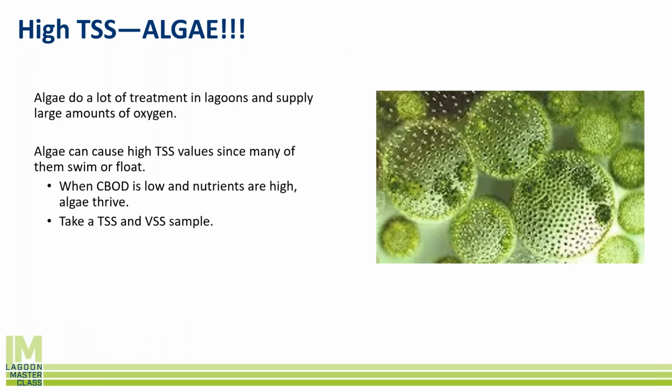So sometimes when we have high TSS, one of the first things we need to do is go back to that previous screen and try to figure out if that TSS is actually volatile solids, or is that TSS non-volatile solids? Is it inorganic solids? Because if it's volatile solids, and you can tell this too because the water might look a little green, that's probably because it's a lot of algae.